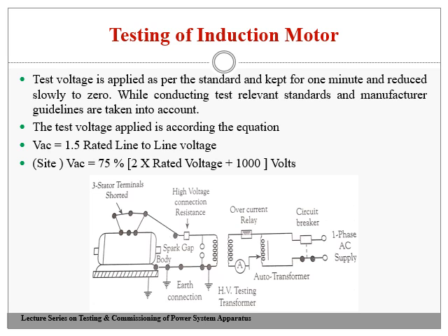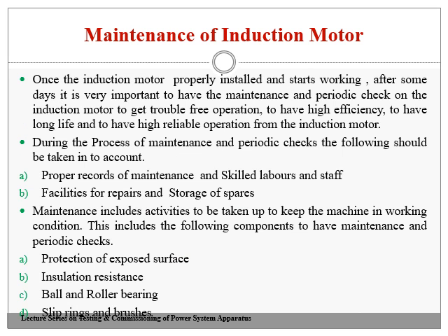It is about the high voltage: whenever you apply the high voltage for a minute or so, as per standard, that particular electrical equipment has to withstand it without any flashover. This is about the high voltage test. Then, after knowing the testing of the induction motor, let us move on to the important aspect to be considered in case of an induction motor, which is maintenance.